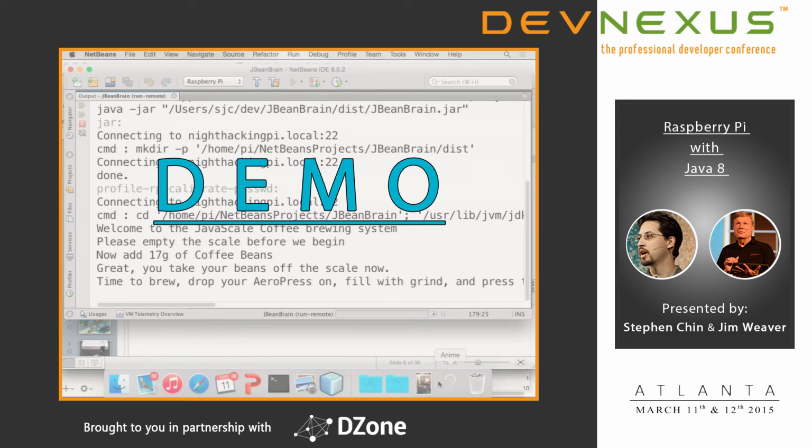And then all you have to do is export as an STL file, and then pop it into Cura, and then you can go and do your slicing.